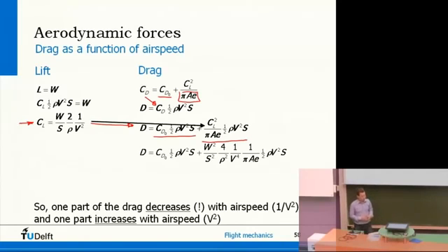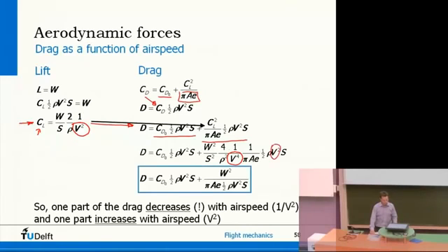So that means that squared, I get airspeed to the power 4, and I have to multiply that with half rho V squared S. So these V squareds, you can get rid of, or rather you get rid of two of them, and this is the final equation you get. So it's a very simple derivation. You just fill in the parabolic lift-drag polar in the lift and drag relations. But this is then what you end up with.